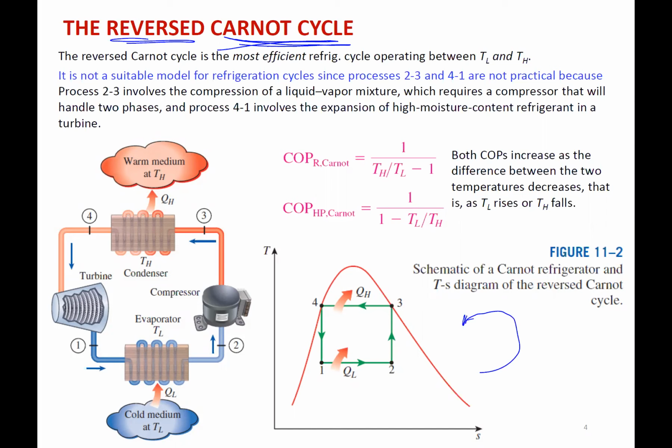Right, and the refrigeration / heat pump, where we have it going clockwise in a heat engine, right? Through the cycles, a heat engine would go clockwise, and refrigeration counterclockwise, because that requires net work in. The heat engine goes clockwise, and that means you get a net work out, right?